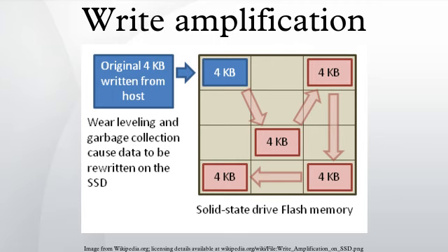The first level of over-provisioning comes from the computation of the capacity and use of gigabyte as the unit instead of gibibyte. Both HDD and SSD vendors use the term GB to represent a decimal GB, or 1 billion bytes. Like most other electronic storage, flash memory is assembled in powers of 2, so calculating the physical capacity of an SSD would be based on 1,073,741,824 per binary GB, or GiB.